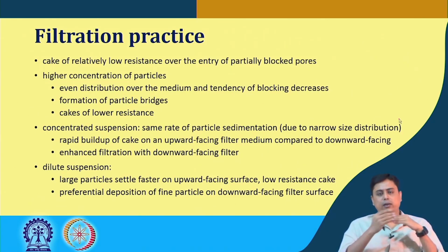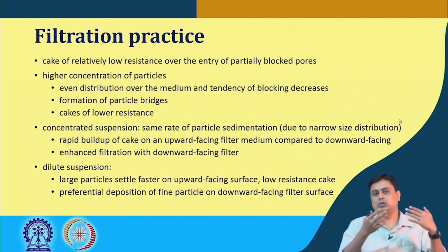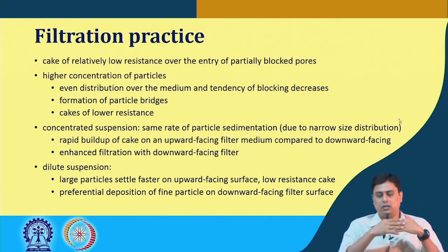But in the case of a dilute suspension, the large particles will settle faster. Now we know by Stokes' law the terminal velocity, and if the larger particles settle faster, you can imagine that the cake will consist of these larger particles, which have a larger voidage, and it will create a low resistance cake.